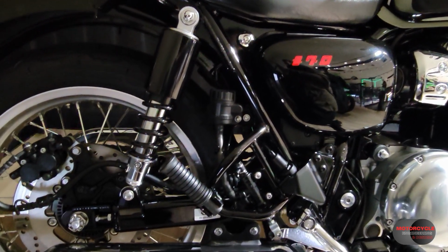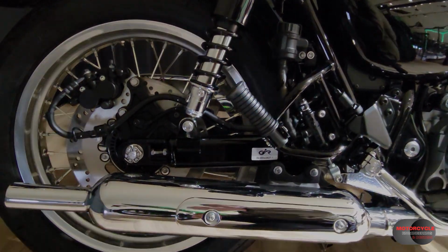So what is the leverage ratio? Well, this ratio describes the relationship between the rear wheel and the RSU, specifically the amount of travel. But it also translates to the forces that the RSU is subject to, that are translated through the wheel. So let's start with taking a look at a simple, directly mounted suspension system.